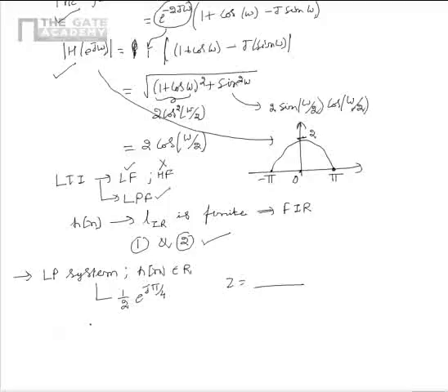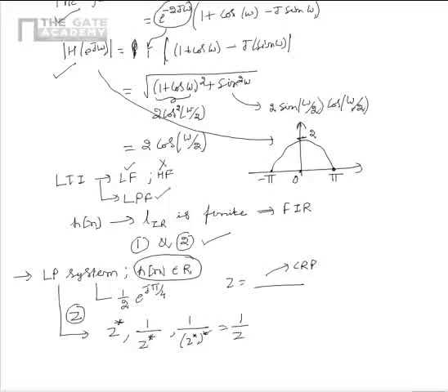From the given data, we see that in case of a linear phase system with real impulse response, if there is a zero at z, then there is another zero located at z star because the zeros are complex conjugates as impulse response is real. From this, we can also say that as the system is linear phase, zeros form conjugate reciprocal pairs. So definitely we can say that there exists a zero at 1 by z star and 1 by z star whole star, that is equal to 1 by z.